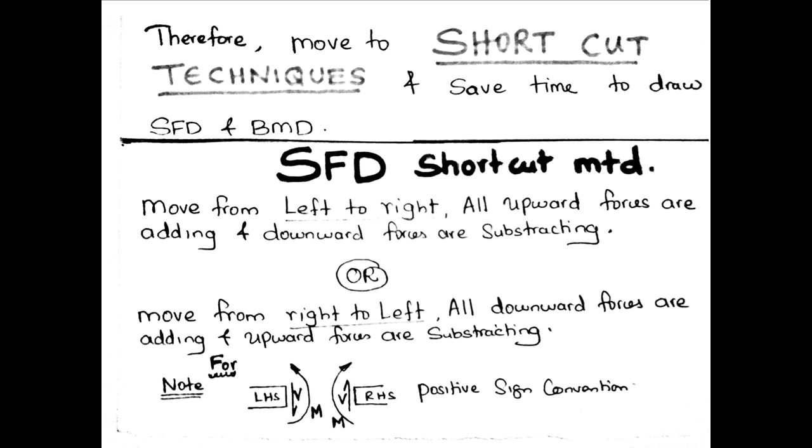Shear force diagram shortcut techniques, actually techniques, not method. Move from left to right: all upward forces are adding and downward forces are subtracting.